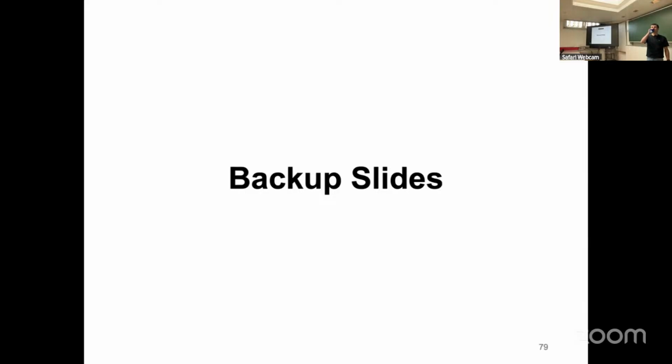If you look at this work, there is still a lot of potential to improve it, because you still have to move a lot of data to the latches and then perform computation there. Flash Cosmos tried to improve it by performing more computation with a single sensing operation, but we are still only scratching the surface in terms of what we can do here.